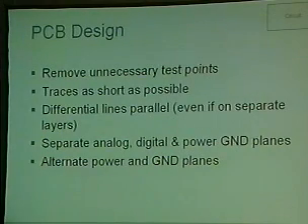So you want to remove unnecessary test points. A lot of times, if you have too many test points, they'll allow unwanted noise and interference to pass through the board. You'll see in these next few slides, I'm going to talk a lot about keeping the EMI and the noise interference down. We'll explain why in a few slides.